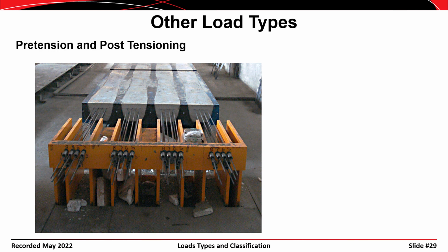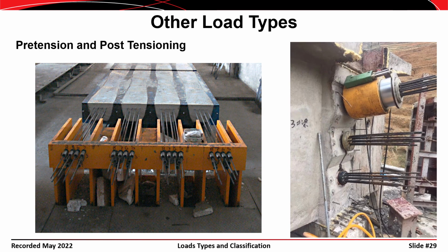and that's called pre-stressing. An alternative to pre-stressing is to cast ducts in the concrete, and then after the concrete is cured, pass a tendon through those ducts and then impose the force afterwards. And that's called post-tensioning, because in that case, the tension is imposed after the concrete is cured as opposed to before the concrete has cured. We have to account for these forces as well, though I don't know a whole lot about post-tensioning or pre-tensioning, I focus mostly on steel structures, but it is important to consider that.